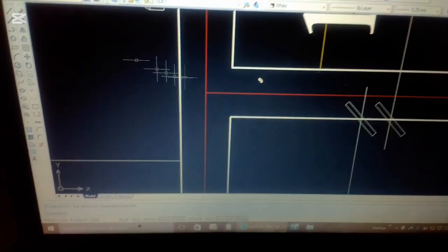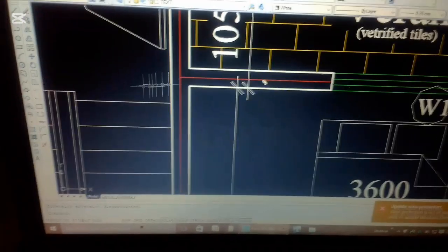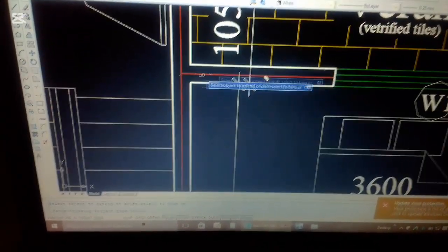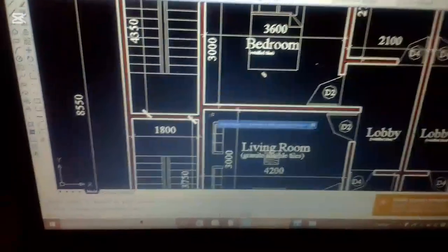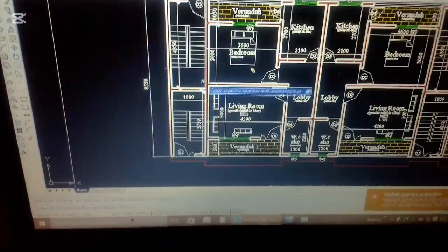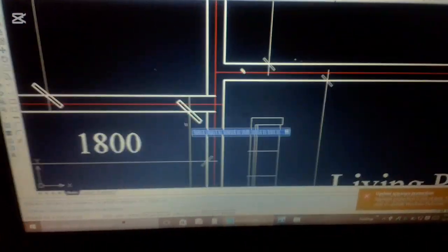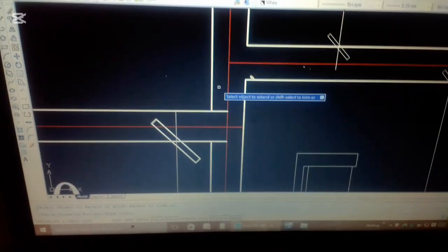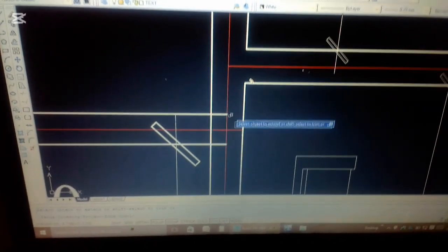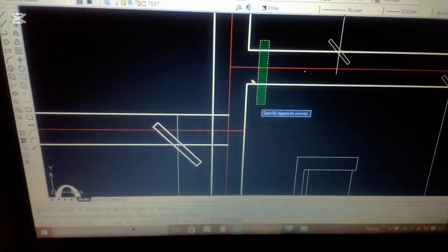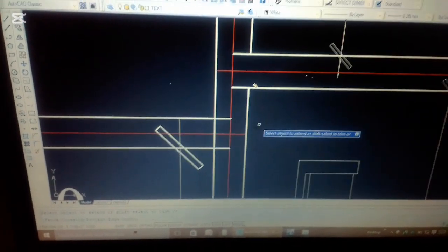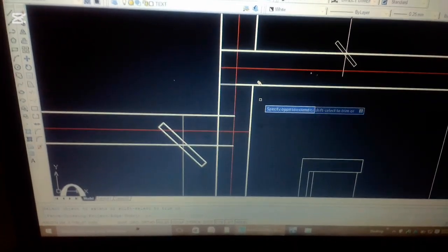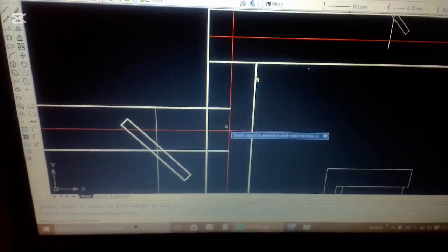I'm going to go ahead and do a lot of trimming and extending of the various lines that are present here. Just an illustration of what to do so that you understand when to trim and when to extend. So you can trim two lines at the same time by swiping on the two lines together. The same thing with extending of lines.